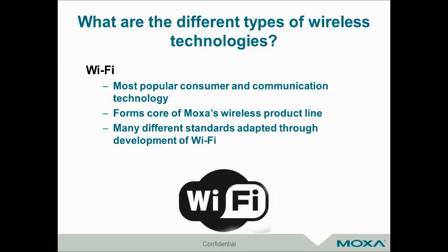The downfall of that is that it tends to have very low bandwidth available. So most 900 megahertz systems, they're also proprietary, but they tend to top out at about 1 to 2 megabits per second. So it's also good for doing remote monitoring of data points or any kind of small bandwidth type of application. So again, not the greatest if you want to send video monitoring back across a long distance. You probably want to take a look at another type of backhaul communication for that type of application.